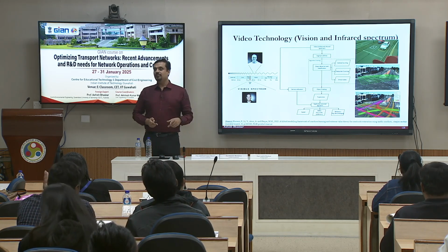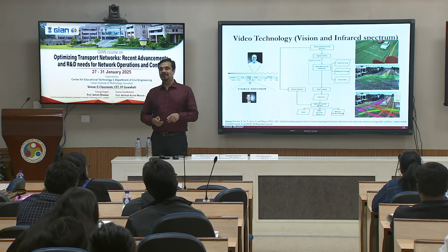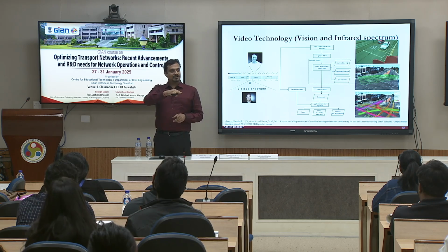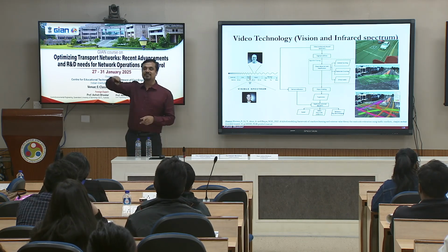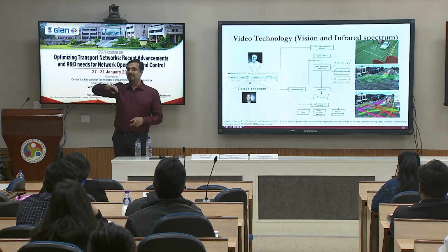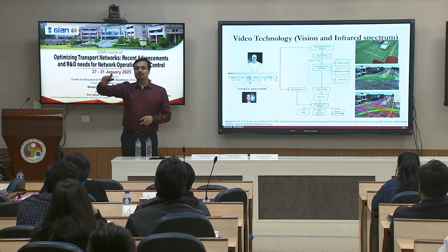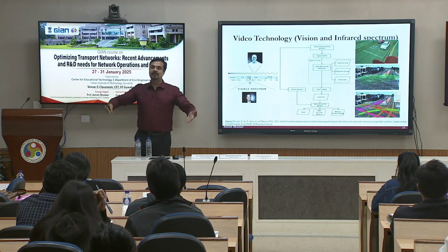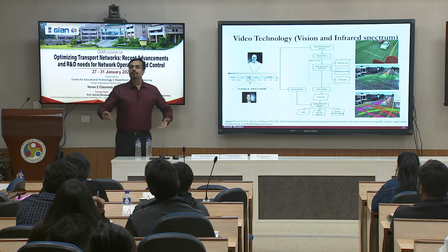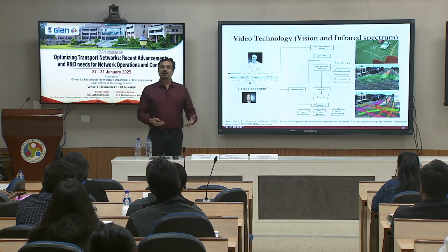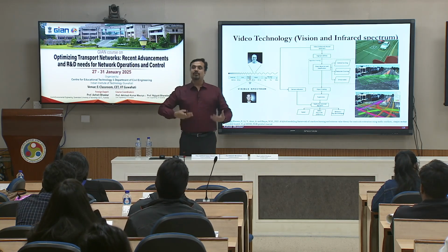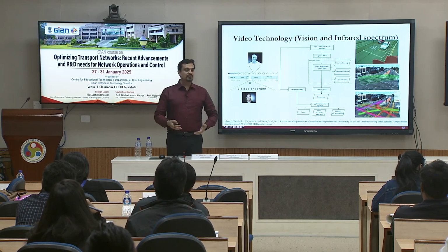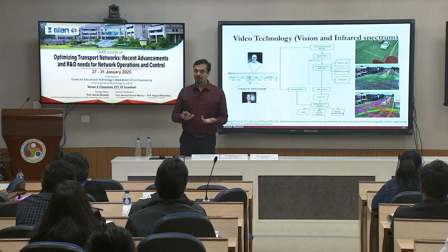It is not easy because travel time and demand have a non-linear relationship. Travel time is fixed for a certain while and then starts increasing, and that demand sensitivity, the fluctuation, is far too high, and it will be hard for you to optimize that way. But yes, travel time can be a good starting point. In the absence of other information, you can use travel time to come up with some smart algorithms with some assumptions, highlighting the assumptions, but then at least there is a way to control it.